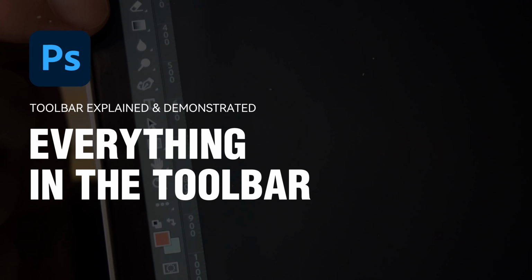There are several options for the marquee tool. Add to selection and subtract from selection are two relatively commonly used functions when a certain area has been selected. You can use the Add to Selection option. The shortcut is to hold the Shift key when making the second selection. It doesn't matter if you are using the rectangular or elliptical marquee tool.